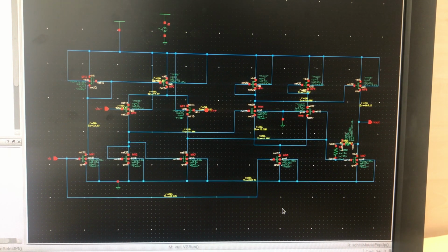Recently finished the course Analog CMOS Design by Professor Atalar. One of the requirements of the course was to design an Opamp which is driving 50 ohm load with a high bandwidth. So what you see in front of you is my design, which consists of 14 transistors, has 3 input pins and 1 output pin. The supply voltage is 5 volts.